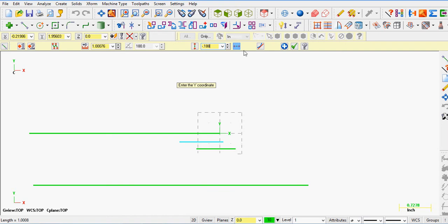Because I'm using the horizontal and vertical commands, this is my last horizontal line I wish to create. I do need to click apply. If I switch now to vertical, my line will change. Okay, so come back, I'll apply it, and now I'll switch to vertical.